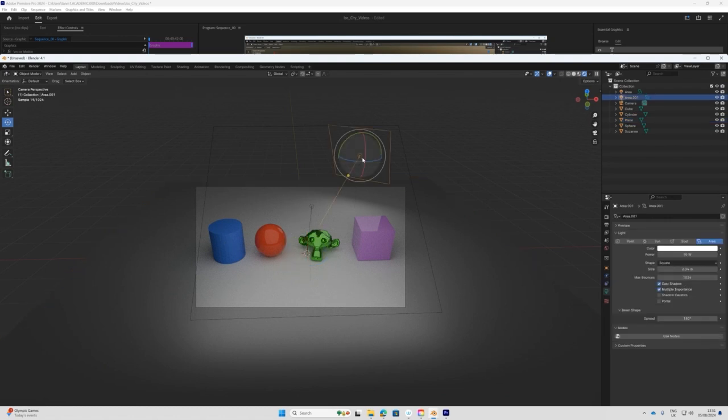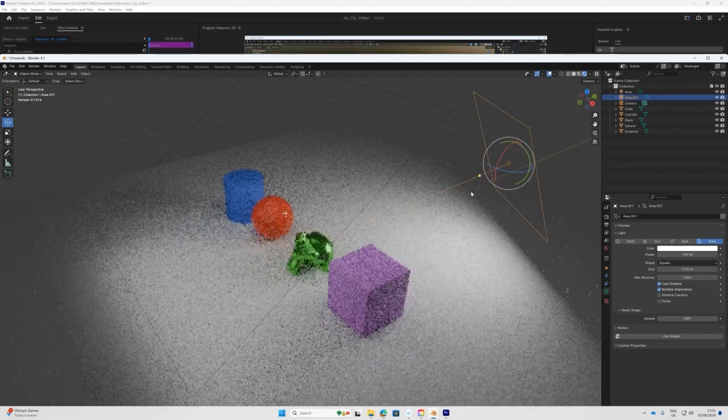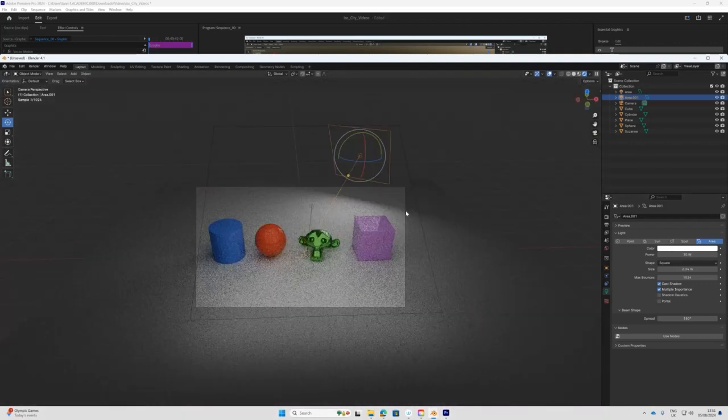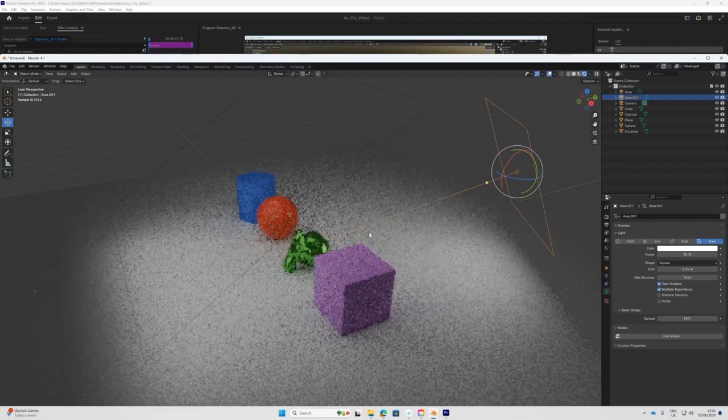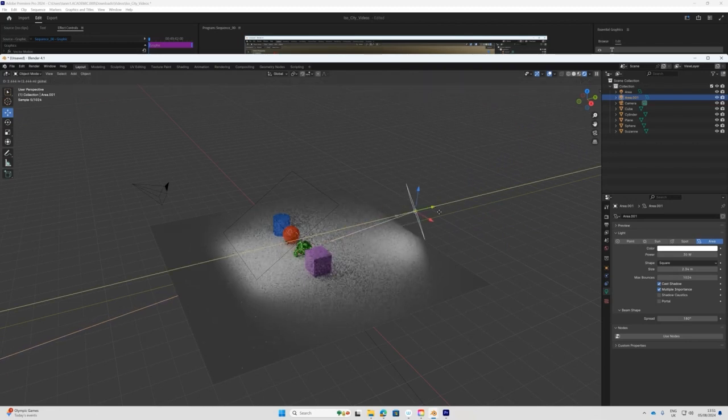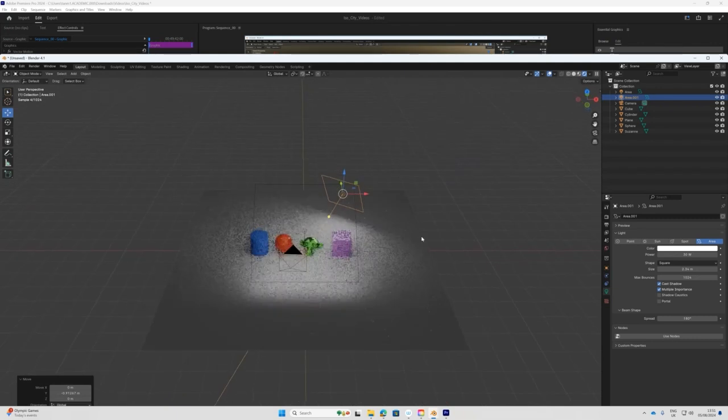These lights are also 10. Just say if I put 100, for example, yeah, it's a lot of light there. It's a lot brighter. And you can see it's creating a very harsh shadow there because it's only emanating light in this direction here. Okay. Actually, I'm going to put 30 here, not a lot. And we can do lighting at some other time with other techniques. And also I want to teach you the environmental lighting, which I will, in doing the exercise. So for now, just going to keep it like that.